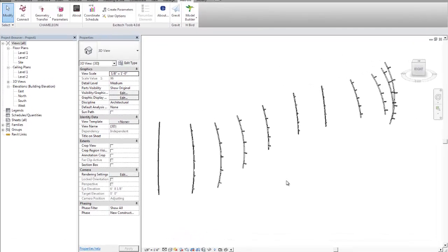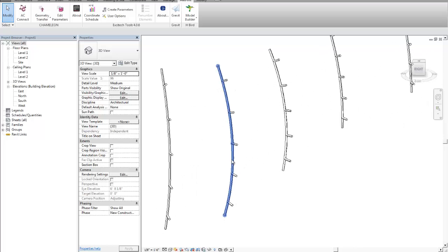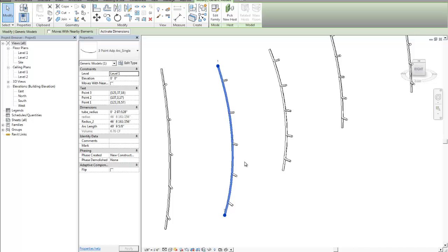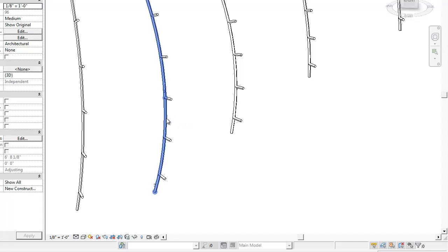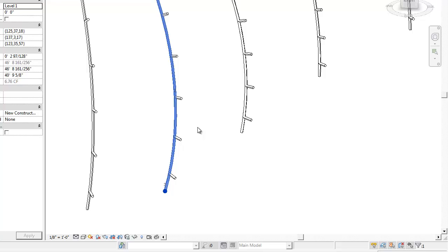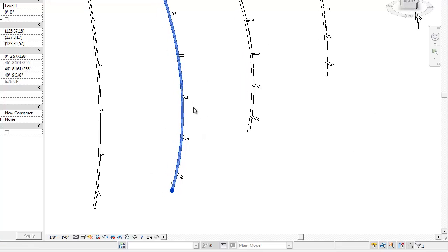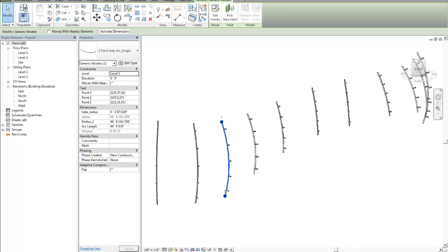So today I'm going to narrow down my focus, and I'm going to show you specifically how to import that geometry step by step, how to create the Revit family, what are the things that you need to look out for, and how to set up your Grasshopper definition to work with the Grevit, specifically, not all of them. So that at the end you get something like this.